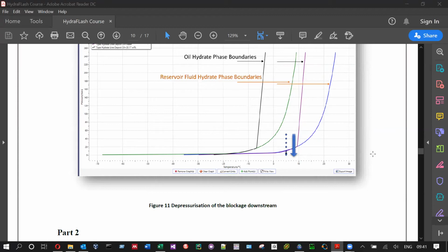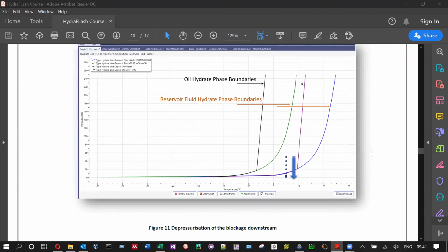When we're talking about a remediation situation where we already have a hydrate, it might be because of insufficient dosing or for whatever reason, then when we start our pumps, we can't really assume a constant mixture of methanol and water content.